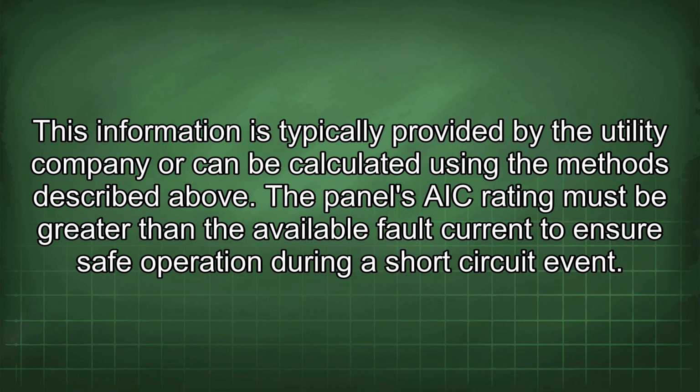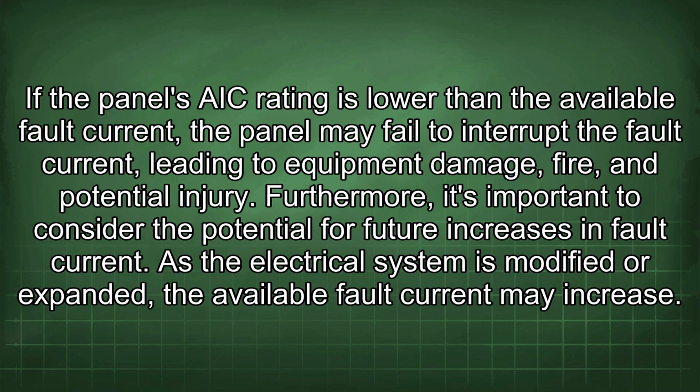The panel's AIC rating must be greater than the available fault current to ensure safe operation during a short circuit event. If the panel's AIC rating is lower than the available fault current, the panel may fail to interrupt the fault current, leading to equipment damage, fire, and potential injury.